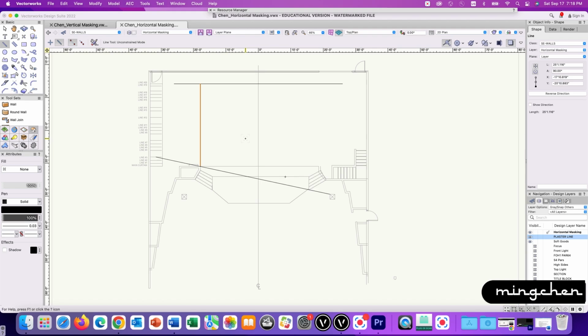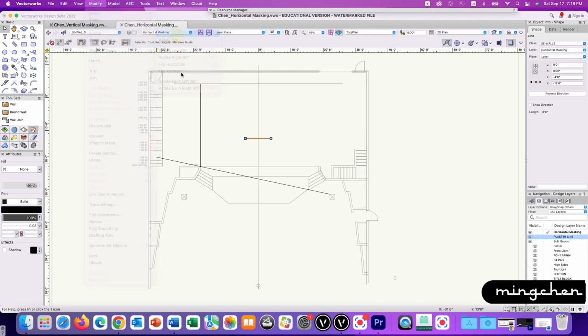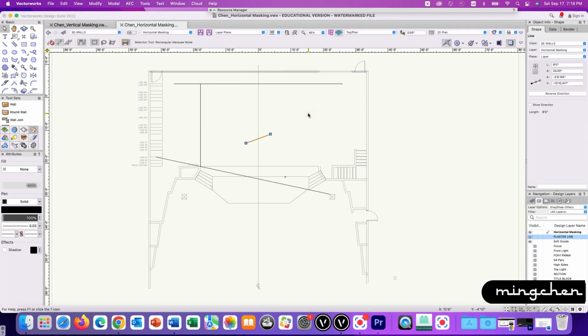To install the first leg, draw an 8 feet horizontal line to represent the leg. Rotate the leg to 20-degree angle to block a wider sideline area. Click and drag the middle point of the line to align it with line number 3 of the baton position. The onstage side of the leg needs to hit the proscenium reference line. Drop the leg in position.